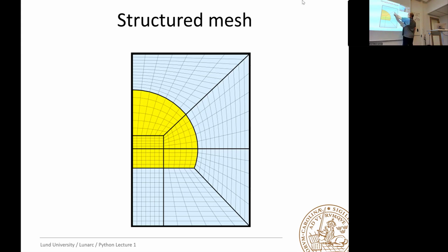When they share geometry, they have the same number of elements on each side. And then you can build, using these Lego blocks, quite complicated structured meshes. So this is a symmetry. This is a tunnel segment here with different materials and different super elements like this.